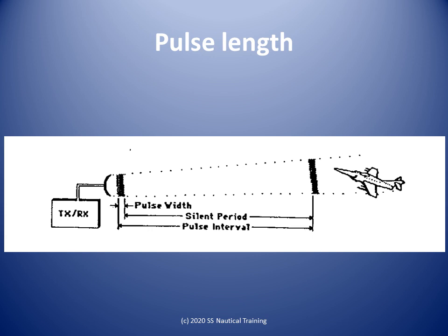The pulse width determines the minimum range at which targets can be detected. This minimum range is approximately 1/2 the length of the wave burst. In the case of the 4.5 microsecond pulse, the minimum range would be 675 meters. This is also equal to approximately 0.36 nautical mile.